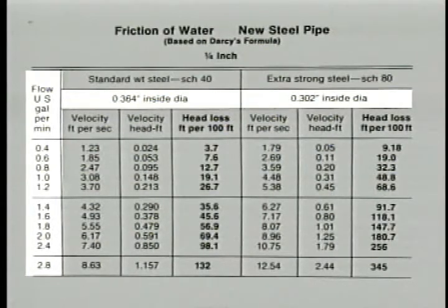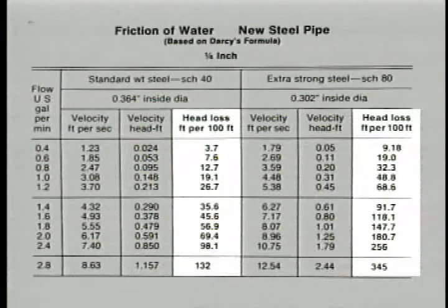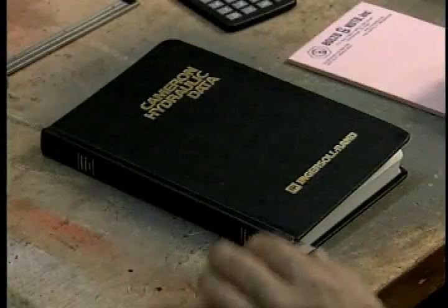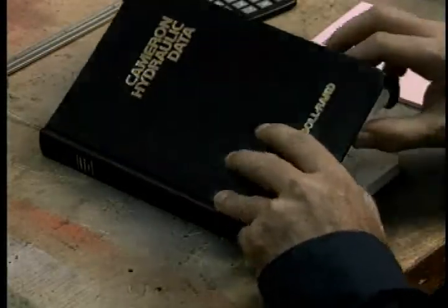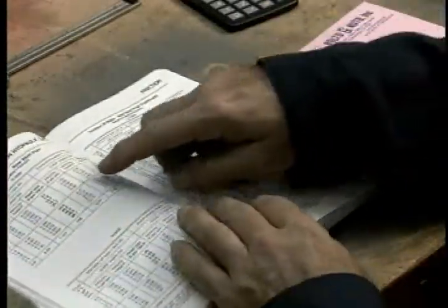This table, for example, indicates that a difference in pipe diameter of just 5/100ths of an inch in a quarter-inch pipe will more than double the friction head. Tripling the flow through the large pipe increases the head loss more than 7-fold. Additional friction loss is caused by the fittings and valves. Information about this part of friction head is also available from reference books.